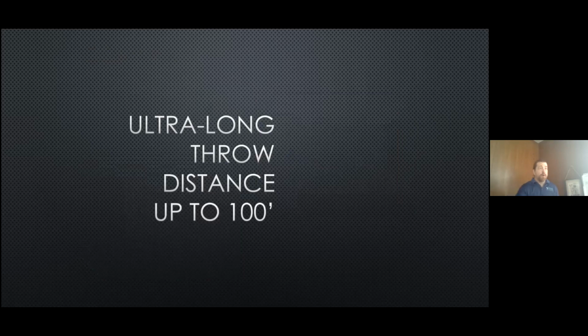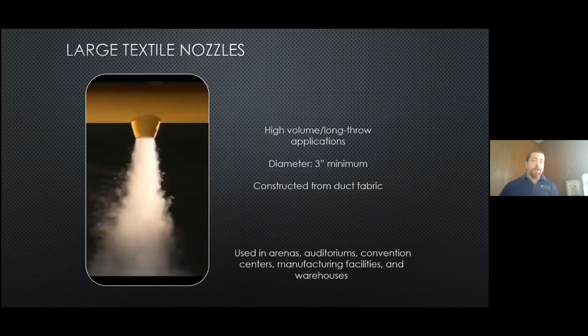Then there are those jobs where the air really needs to be moved a long distance. We're talking out 80, 100 feet. This is when we move into a slightly different design nozzle, but again, something that's really easy to accomplish. These are also manufactured from the same fabric material, same polyester that the diffuser itself is, but these are stitched on rather than being an ultrasonic connection. Those smaller nozzles that I showed you, those are ultrasonically welded to the diffuser. These are going to be stitched on, and they incorporate small manual dampers that could actually be used to completely shut off the airflow from each of the nozzles if necessary.